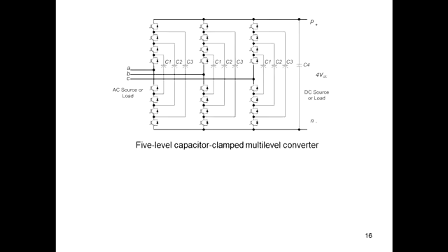So there are other types of multi-level converters which are in existence, but the very popular one is the cascaded H-bridge. I don't have the circuit here, I didn't have time to do that, but I'll post it. Within a week or so you will get the figures here. Dual active bridge is also a bidirectional power converter, which involves 2 bridges. It can be called a DC-DC converter with bidirectional power flow. The DC-DC converters that we showed previously can only allow power flow in one direction, the basic DC-DC converters.